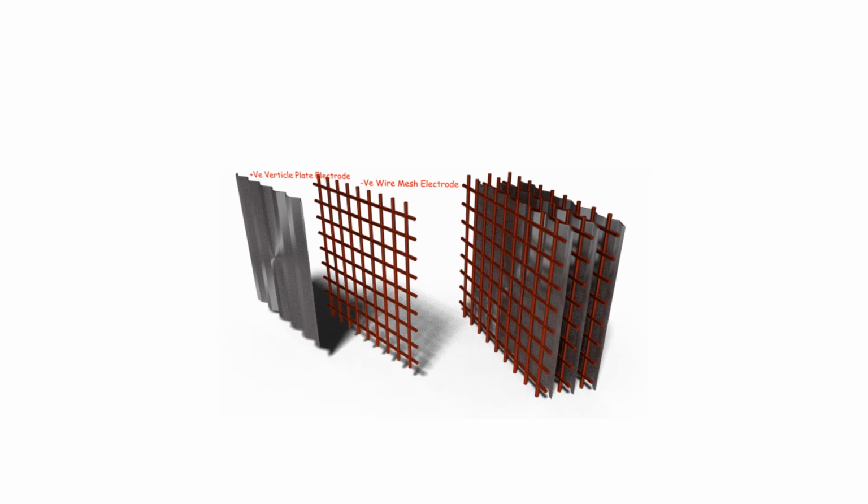Here we have to note one point, that there are plenty of free electrons as the electrodes are ionized, which interact with the dust particles of the gas, making them negatively charged. This is the basic concept, an important point we have to understand: free electrons are many in between these two positive and negative electrodes.